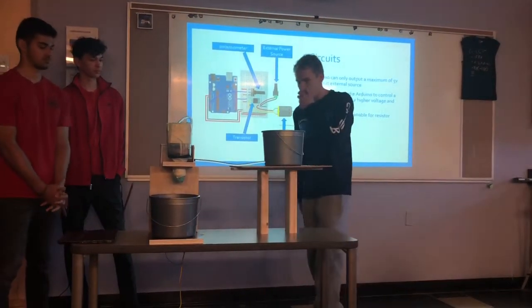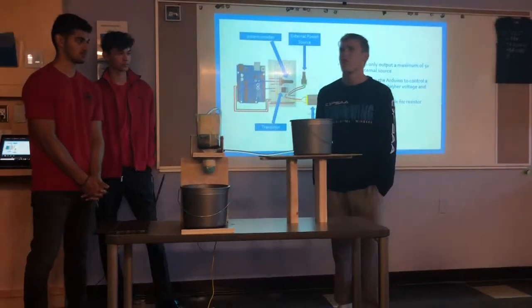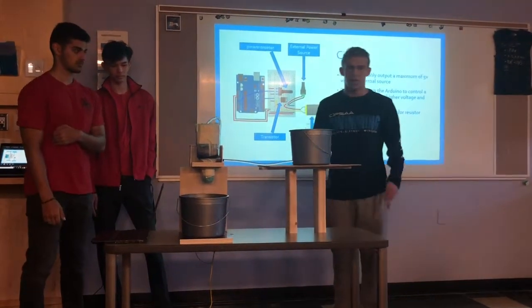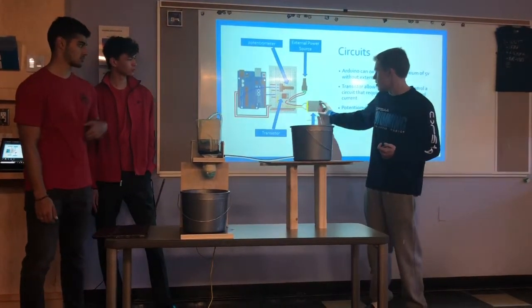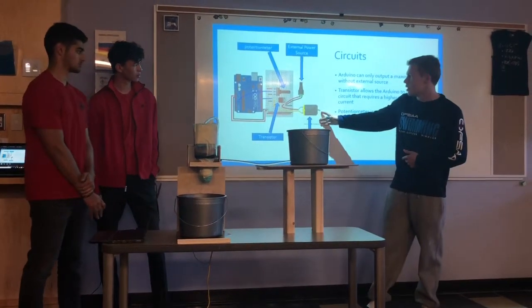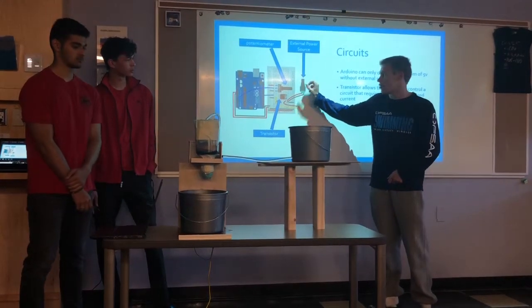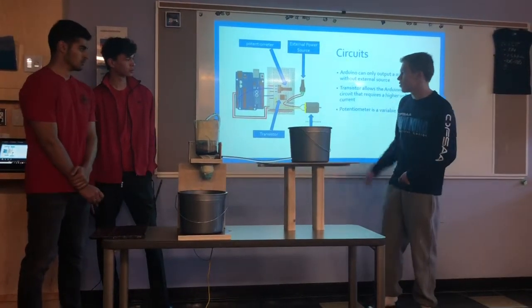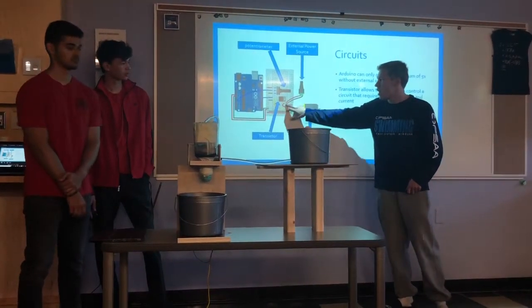So we ordered a pump, which is just attached here, which requires 12 volts, I believe it was. So this is the pump here. The 5 volts from the Arduino was not going to be enough to power the pump. So firstly, we had to install an external power source. We took two 4-packs of batteries, so 8 batteries, that's 9 volts, and connected that to our circuit.